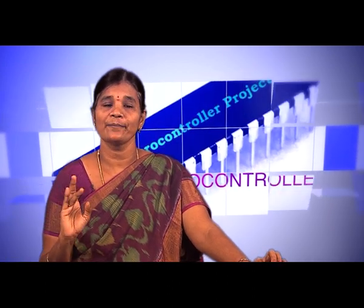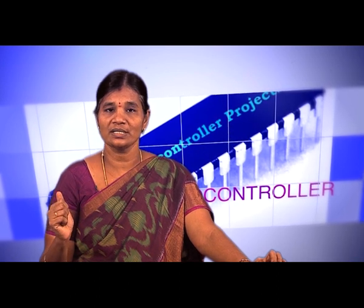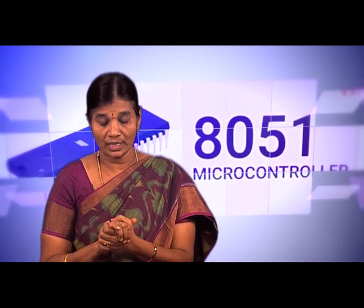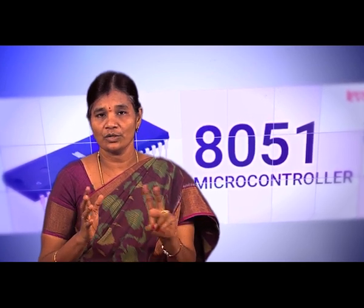Whether these 4 are possible using the 8051? Yes, we can perform addition, subtraction, multiplication and division using the 8051. Compared with the 8085, only addition and subtraction are possible, there is no multiplication and division. So, here we have 4 kinds of operations. Not only the basic 4 arithmetic operations, we can also increment the registers or the content, either memory or register. These kinds of instructions will be discussed in today's session.